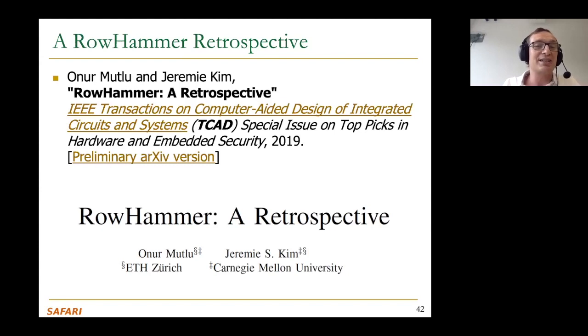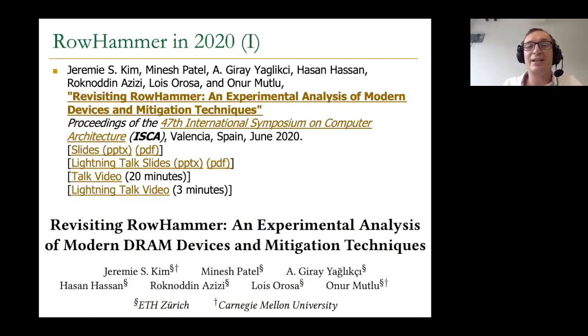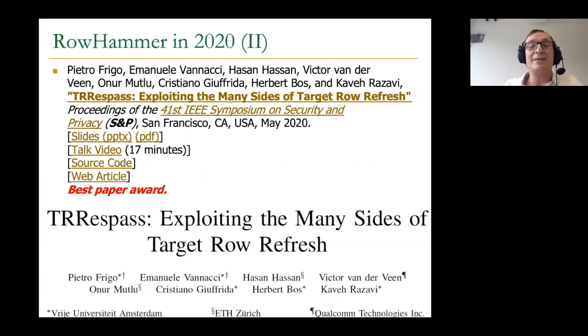And as I mentioned in the last lecture, maybe people were thinking, okay, Rowhammer's gone away, but it's really not gone away. It's really still a problem, as this paper has showed, with fundamental observations on real devices. And the solutions that DRAM manufacturers say are Rowhammer free. Basically, manufacturers actually advertised recent DRAM chips saying, oh, we have a solution to Rowhammer. Internally, these are not vulnerable to Rowhammer. Okay. And they never said anything beyond that. Basically, they never said how the solution works.